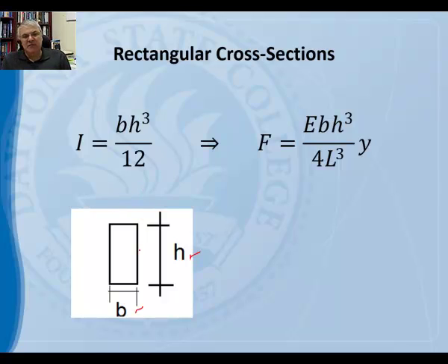This one has higher, so it's more difficult to bend a beam with this cross-section if we apply the load exactly at the tip on top, whereas if you turn it around to the side, more like a ruler, then you can easily bend it, and that is because we have a smaller moment of inertia. Again, we are dealing with engineering, and everything has been formulated, and there are both mathematical principles behind it and also experimental data.